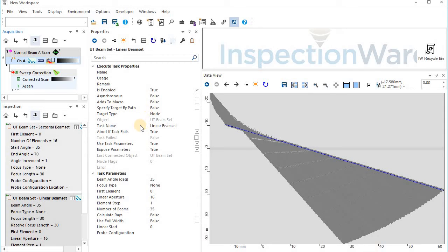and what it does is it fills in this description, and then it goes under the hood, runs the focal law calculator, goes and gets the probe and asks the question, if I want to run from these elements, these 16 elements that I'm running, and I want to run a beam at 35, 36 degrees, what delays do I need to put on my elements?